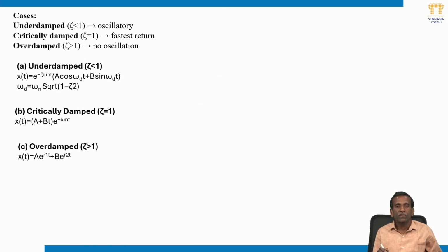Okay, so when damping is also considered, it comes under free damped vibrations. If zeta is less than 1, meaning c is less than 2 square root km, it is called underdamped vibration. It means the resistance force from the external agency is less effective on the oscillatory motion, so the oscillations continue.